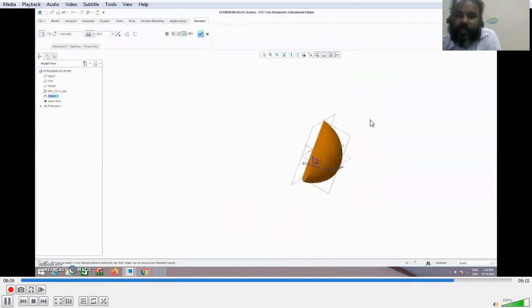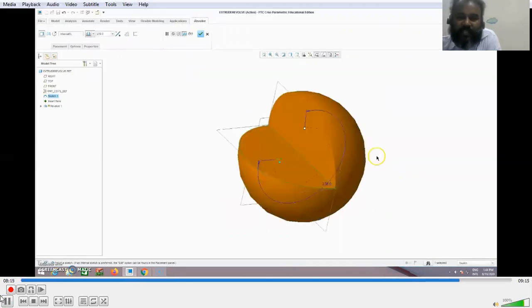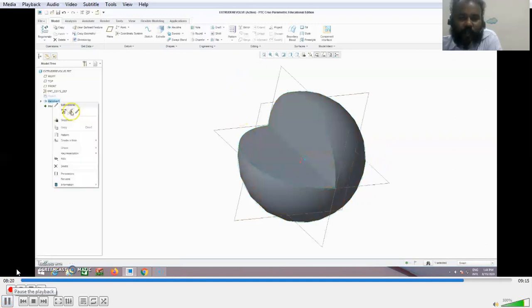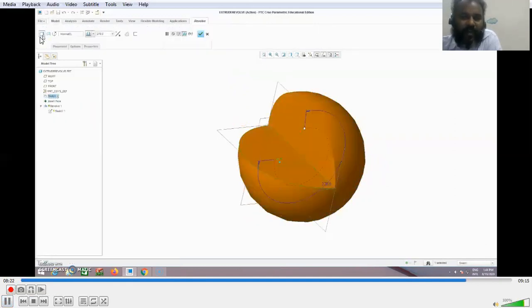You can revolve it to a particular angle for us to see the cut view, what is there inside. If you see, it is like a solid filled sphere. You can make it hollow also. How to make it hollow? Like a thin shell of a plastic ball that we play with. That will also be explained here. So go to the edit option. Once you click the edit option, you have two options here. One is to have a solid, one is to have a shell-like feature.